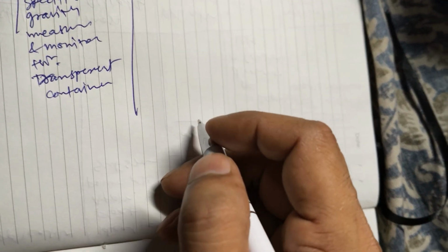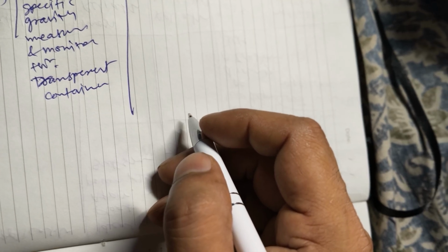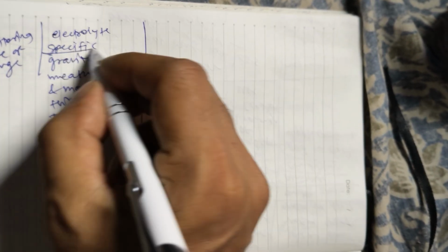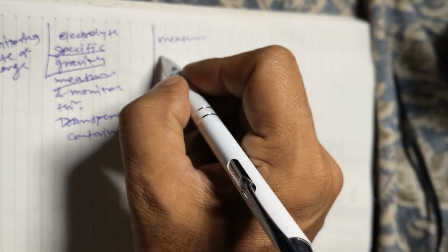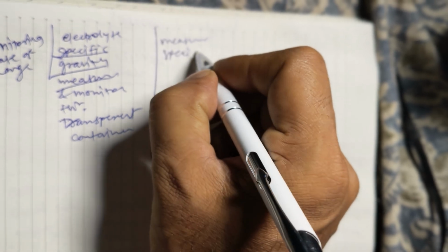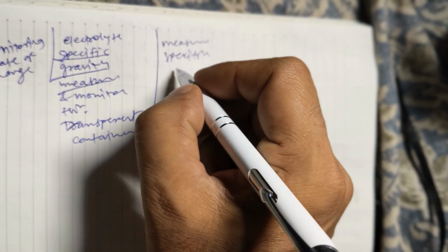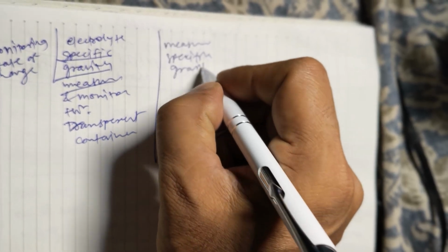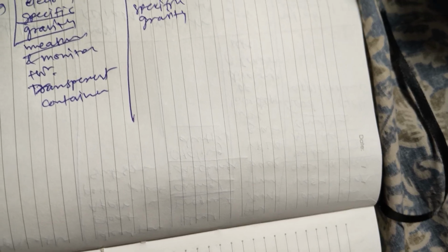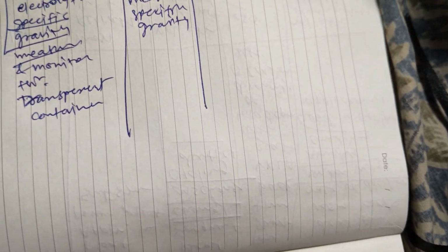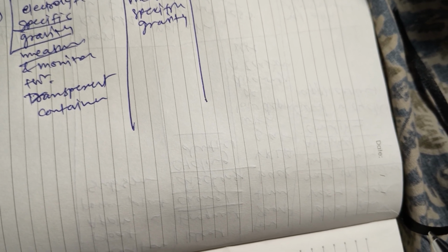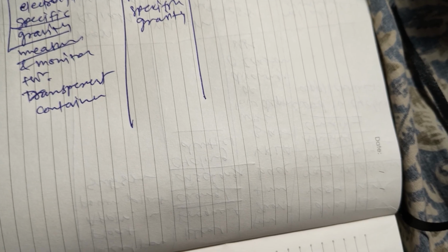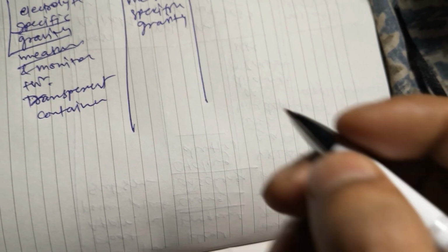In tubular type battery, it can be done by measuring electrolyte specific gravity. In VRLA, no easy method to ascertain the state of charge. Since the cells are completely sealed, the cells act as black boxes.